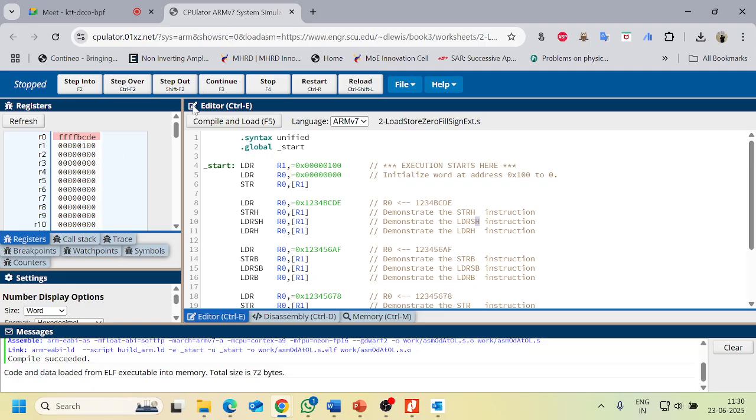Next, SHR. Again, what are we doing? It is an unsigned number. Unsigned number means directly your BCDE is going to be loaded. The sign extension will not be done. Even though the MSB bit of B is 1, that will not get extended. Understood this?